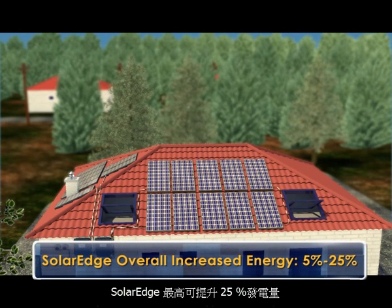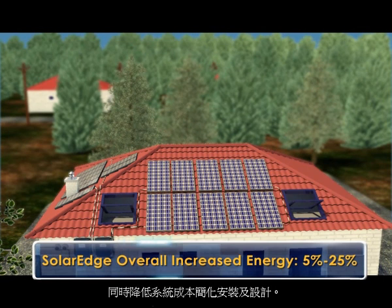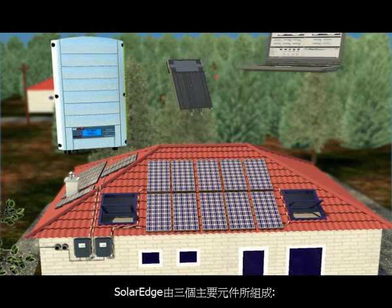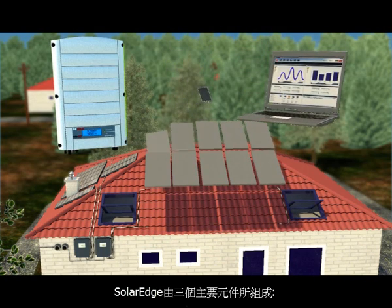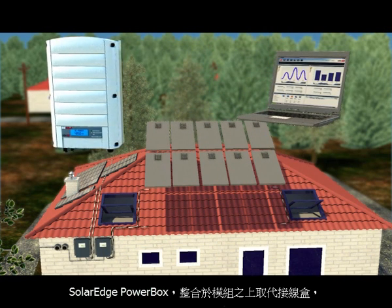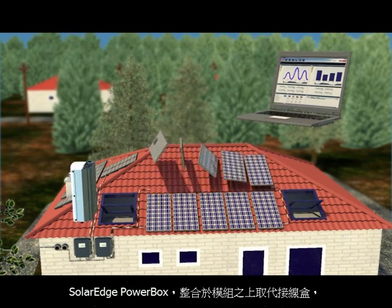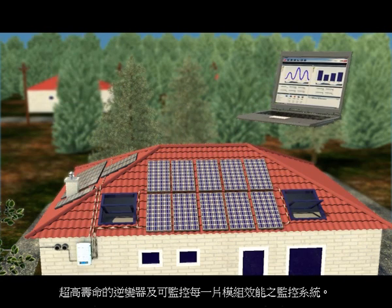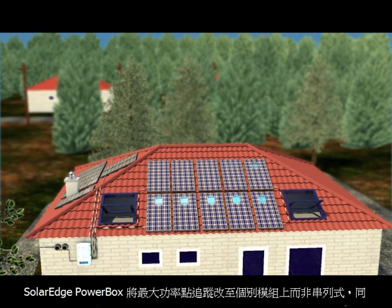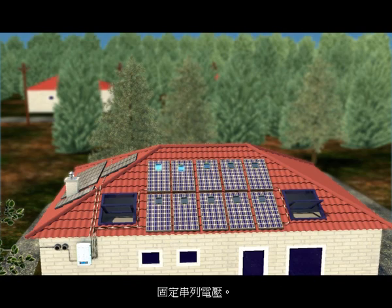SolarEdge increases energy output by up to 25% while reducing system cost and simplifying design and installation. The SolarEdge system is comprised of three key elements. SolarEdge Power Box, which is integrated on each solar module in place of the junction box. A simplified, highly reliable inverter, and an integrated panel-level monitoring system. The SolarEdge Power Box optimizes power harvesting by performing MPP tracking for each panel individually while keeping the string voltage fixed.